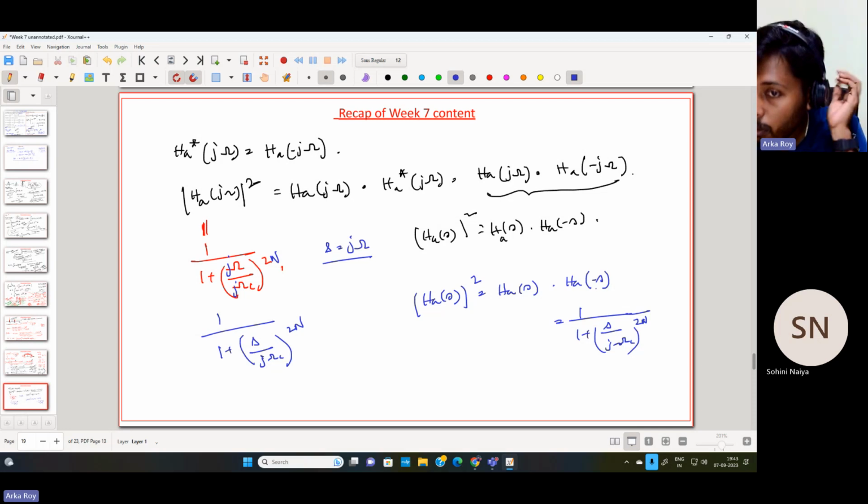And now we have got some representation which resembles a transfer function. Using this transfer function representation, we now need to check the poles of the system, because if the poles are in the negative half, we can comment about the stability of the system.